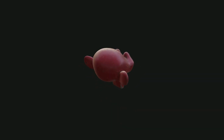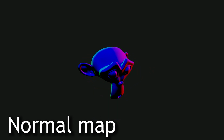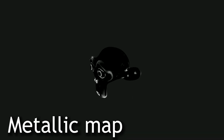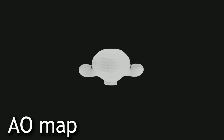At the core of PBR textures are a set of texture maps that collectively define the visual characteristics of the material. Those maps typically include albedo, or base color, or diffuse map, the map that represents the color of the surface. Normal map encodes surface details to create an illusion of complexity without the additional geometry and therefore render times. Roughness map controls how rough or smooth the surface appears. Metallic map defines whether the material is non-metallic or metallic. Ambient occlusion map simulates how ambient light is occluded in corners and cavities, adding depth to the texture.